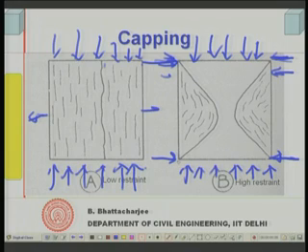But as you go away from this point, the effect of this restraint reduces, and therefore the effect remains practically only up to a certain distance. This is because the restraining frictional force is applied only at these surfaces, which does not allow it to bulge out. Similarly, here. So, this force gradually reduces as you go from the surface of the cube to the inner side, and that is why this pattern is something like this. We will have more understanding of it further.